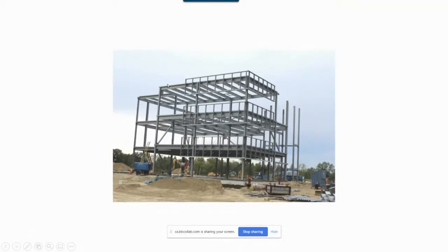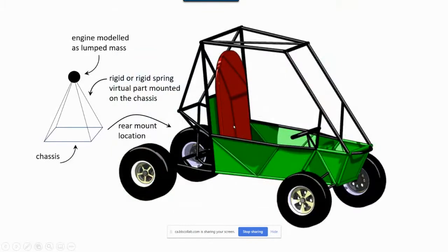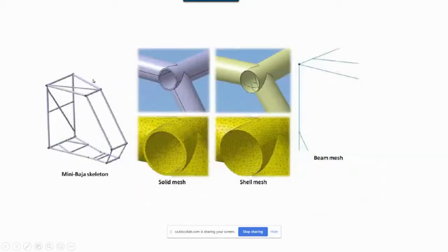So you don't solve this type of problem with the element that I showed you. Or the other one is right here: your favorite Mini Baja or Formula One, or for that matter, aero, your airplane wing, whatever. Now, I have seen people taking this frame and breaking it up into solid elements. Look at this. Because they can't handle it, they put one layer of elements through the thickness, and then you get good-looking garbage, nice colors, nice numbers, with no meaning whatsoever.